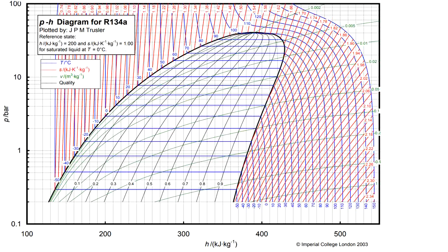Then the green ones are the values of the unit volume, and an important value for us will be the red one, which represents the curve of constant entropy. And the curves of constant entropy are important for the compressor, where the ideal compressor is isentropic.